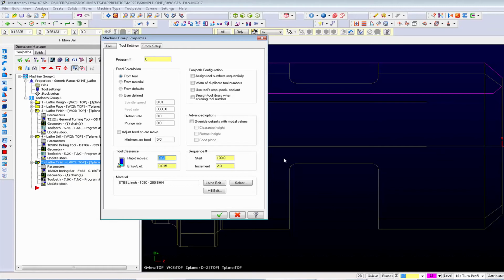One thing you need to be aware of that's especially important here is if you are working in a tight bore, these values can really hurt you because it will try to be smart and you can end up actually smacking the back side of your tool, because it's trying to give you 30 thou of clearance on the front of your tool as it's exiting the bore.